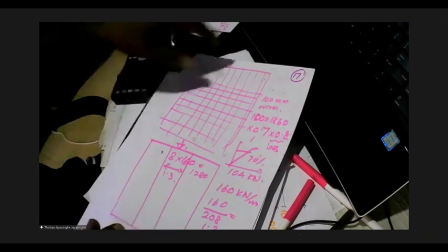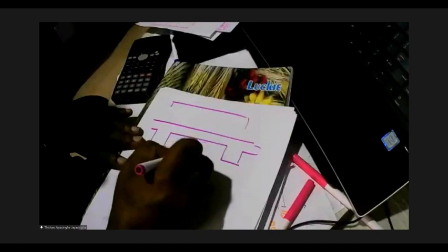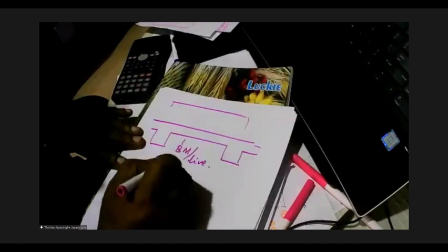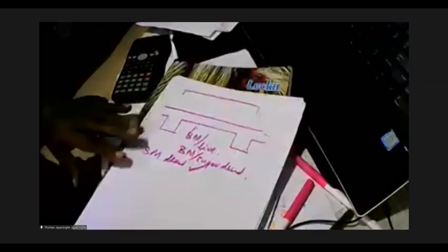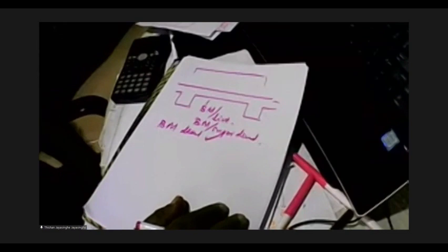So simply supported or continuous is not a major problem, because now you know even if it is continuous, you can find the bending moment due to live load, bending moment due to super dead, bending moment due to dead, all looked after by the PT with load balance. So because of that reason, even if it is continuous, you can design the slab system supported by a set of beams.